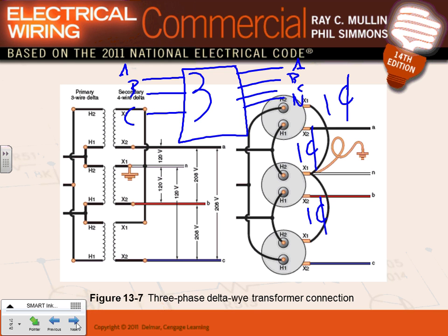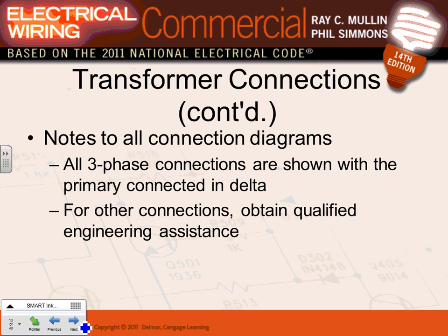And this will be the transformer inside, say, 500 kVA. That's what you get from Xcel. A pad-mounted transformer, typically for a building, is a 3-phase transformer. Can I have a thumbs up, Chad, that this is a 3-phase transformer? This is the rule; the exception is the single-phase transformers. If you have a little shop, a little strip mall, you'll see things like this. But if you have any type of commercial building, you're looking at a 3-phase transformer. I need a thumbs up, Chad, on that one. Okay, so that's my 3-phase transformer.